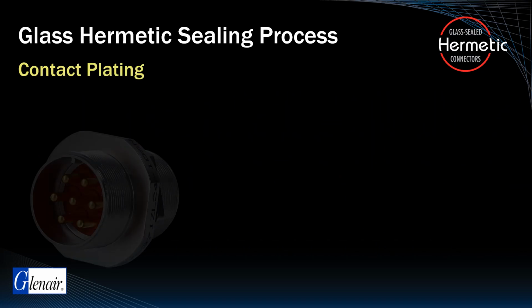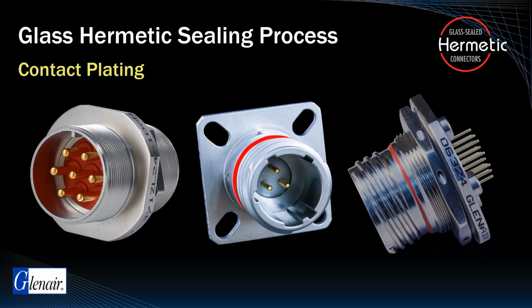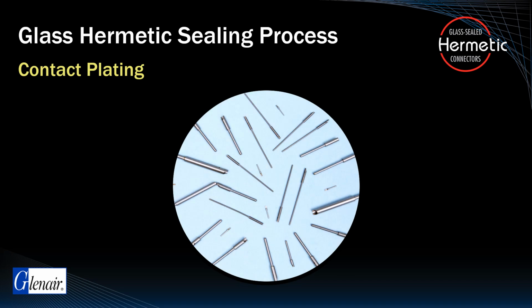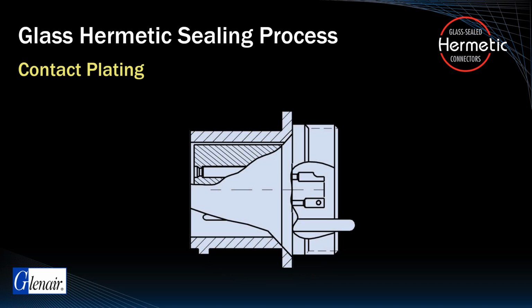At this point, plating is applied to the connector contacts. Without the benefit of surface plating, contacts would not be conductive enough to reliably transmit data or power. For that reason, the contacts, and the contacts alone in a hermetic assembly, must be plated with a conductive material, typically gold. Glass-sealed connector contacts are typically made from Kovar or specialty nickel-iron materials like Inconel or Alloy 52. In this process, each contact is individually wired twice, once on the mating interface side and again on the wire termination side, and the assembly is immersed into the plating solution.